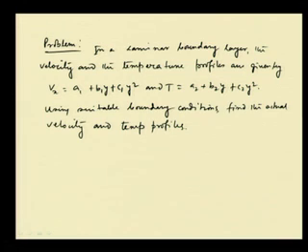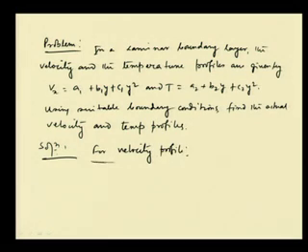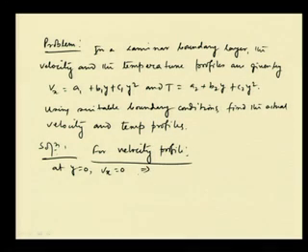Okay. So, now we see that for both the velocity and temperature, the polynomial is a third order polynomial, and we have to find the values of 3 constants for velocity as well as for temperature. So, we need to put three boundary conditions. For the velocity profile, we will put that at y equals 0, V x equals 0. This implies that A1 equals 0.